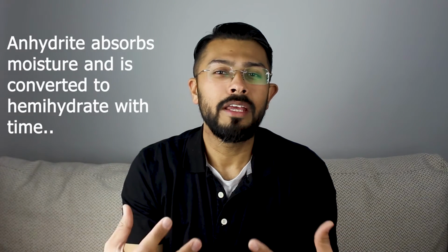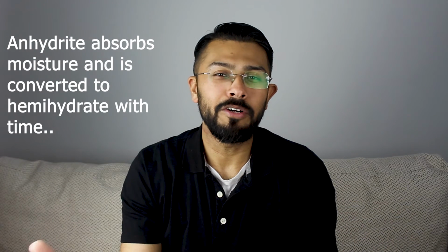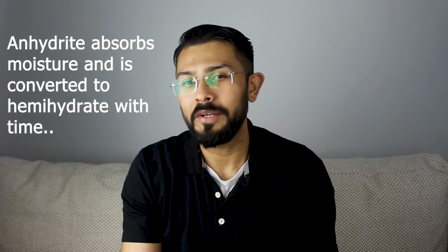Freshly produced plaster may contain significant quantities of anhydrite, and this may accelerate setting to the extent that manipulation becomes difficult. To overcome this problem, plaster is often allowed to mature before use. The anhydrite absorbs moisture and is converted to the less reactive hemihydrate with time. If the plaster is allowed to mature for too long in a humid environment, the hemihydrate crystals become coated with a layer of dihydrate, and the reactivity is markedly reduced.